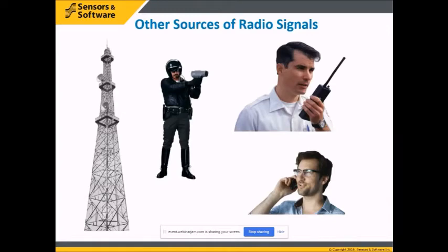The surface of the earth is immersed in radio waves at all times. So you will always see RF noise in your GPR data, even if the antenna is shielded. Now keep in mind that the RF noise is usually about 1,000 times weaker than the GPR signals we are transmitting. So you don't see RF noise until the GPR signals attenuate down to the noise level.